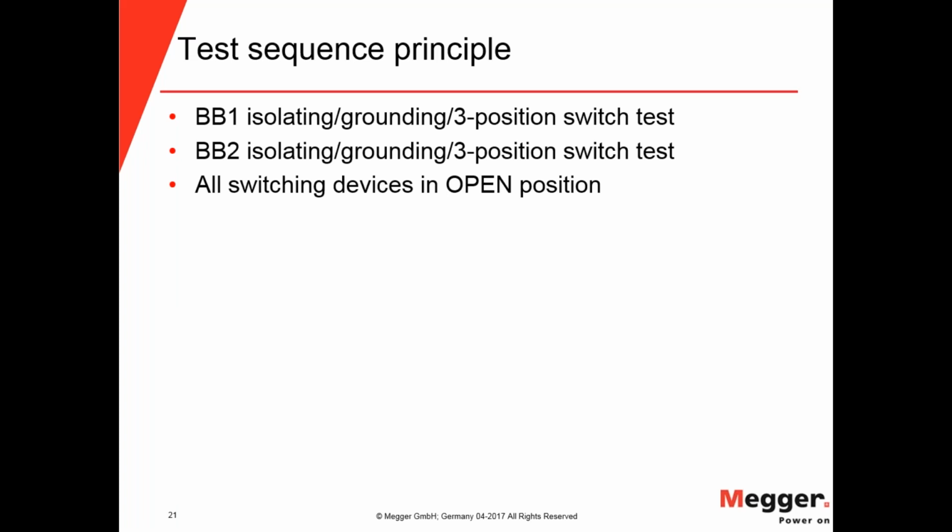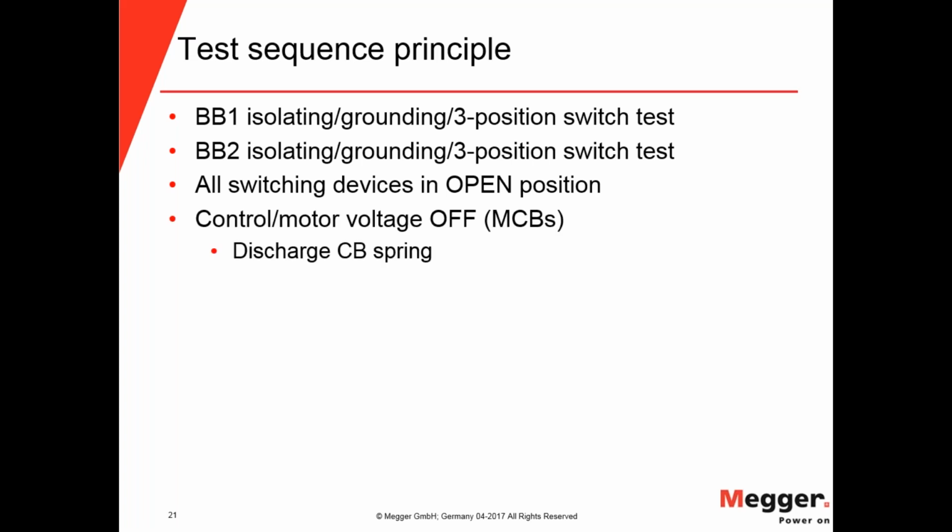And then this part describes how you can attach a transducer. You have all switches in open position, and you turn off the micro circuit breaker for the motor control voltage, and then you can discharge the spring of the circuit breaker.